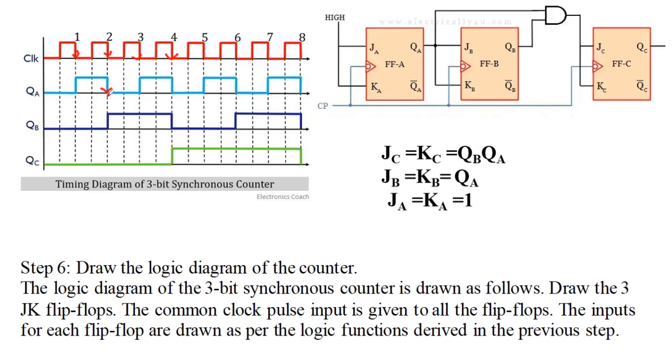Next, on the second clock pulse, QA is logical 1, so the second flip-flop obtains JB, KB inputs equal to logical 1, hence the previous state 0 is now toggled to the logical 1 state on QA.